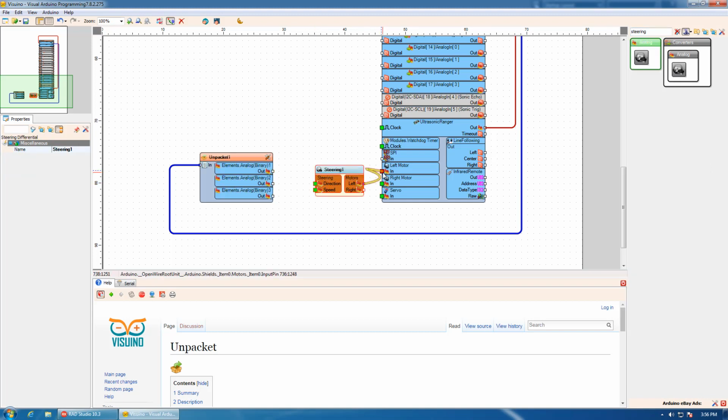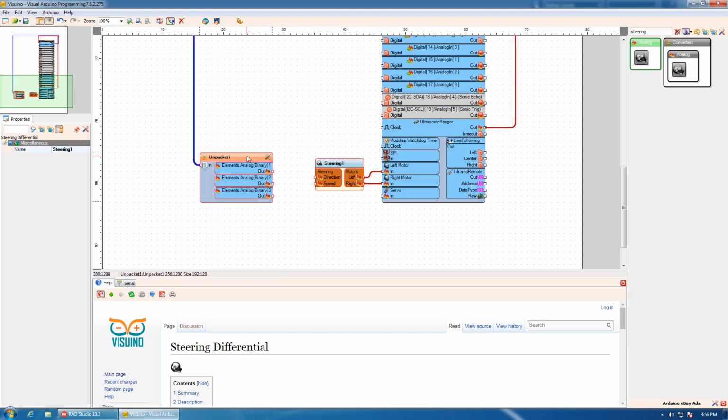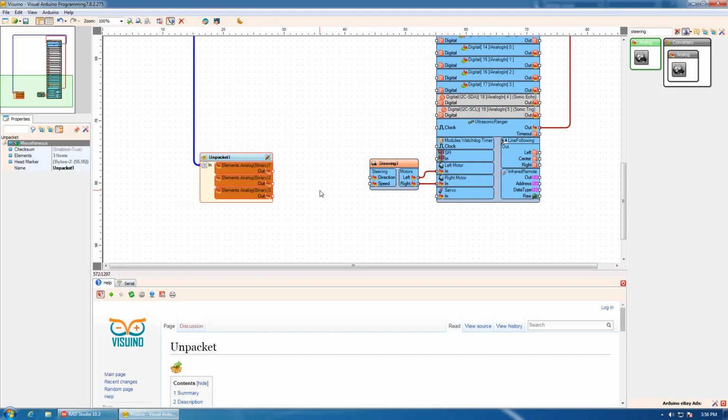I will add the component and I will connect the left and right channel to the 2 motors. The accelerometer will send values between -1 and 1. We will need to convert them to values between 0 and 1 to control the speed and direction. We would also like to have some insensitivity to make sure that when the phone is nearly horizontal, the robot will not move around. For this, we can use the dead zone scaled component.